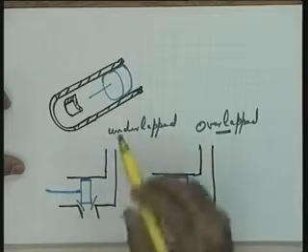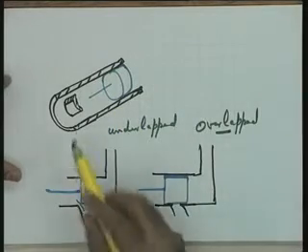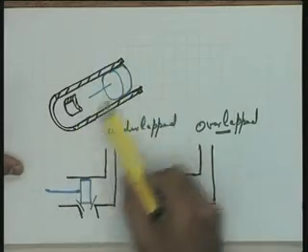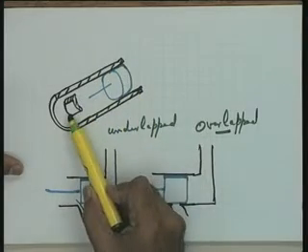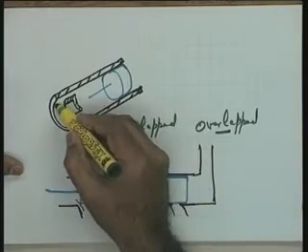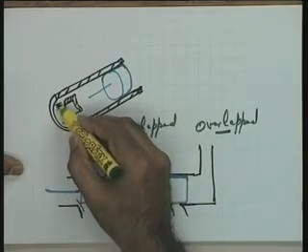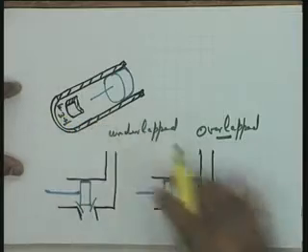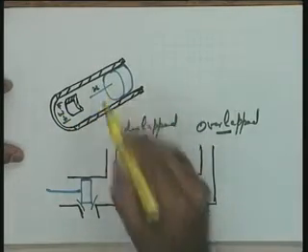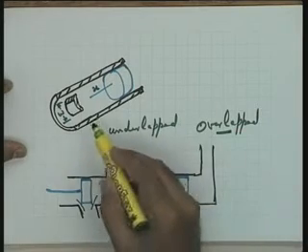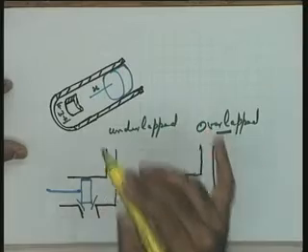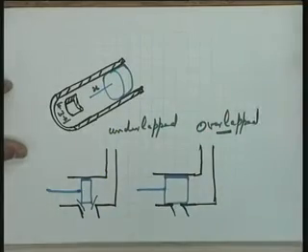In this particular case, since this slide is there before you, I will show you this also. This shows the movement of the piston, and this is the port. Please note the movement of the piston and the port. If I say that this width is W, and this movement is, let us say, x, then W is a constant and the area covered or uncovered is directly proportional to x.